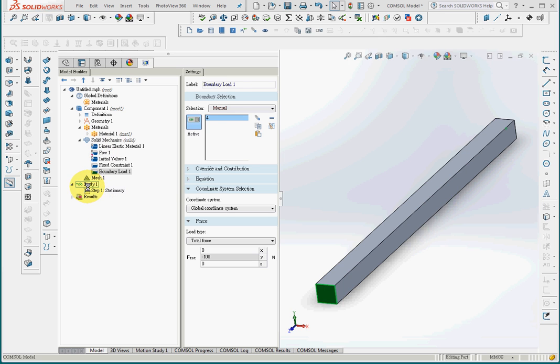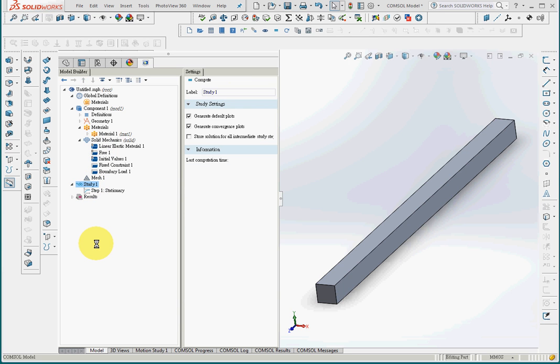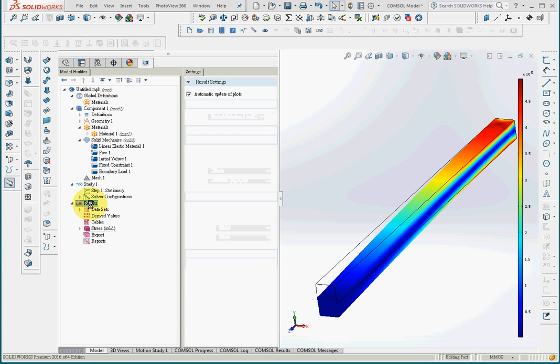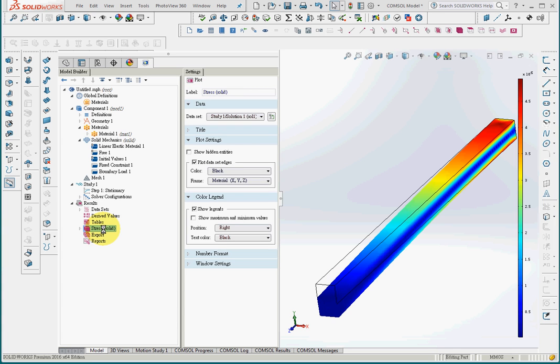So now I have finished with defining the 4 steps on CAE analysis, and these are called preprocessors for the analysis. Up to this point, the whole problem was fully defined, so I'll go ahead and run the study or compute. And this is the 5th step, or step 5 of CAE analysis, and step 6 is the result, and the default result is the stress.